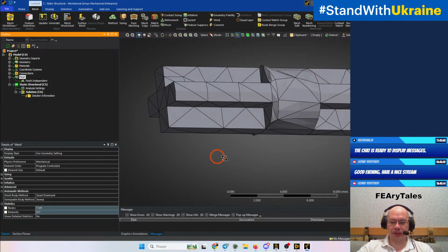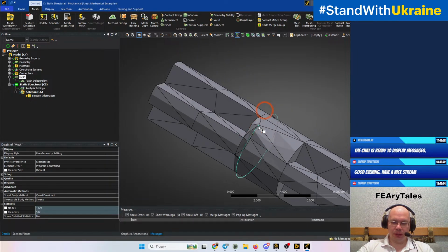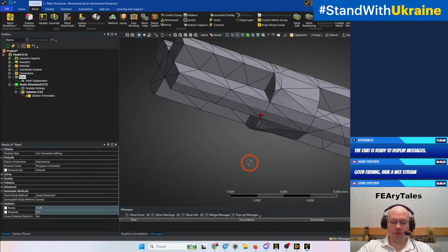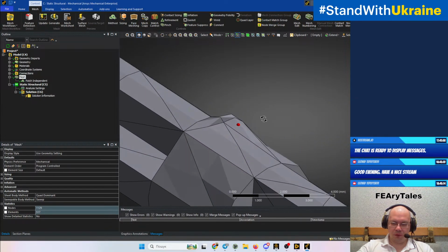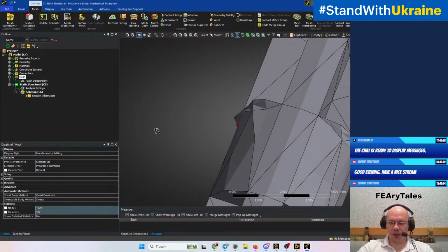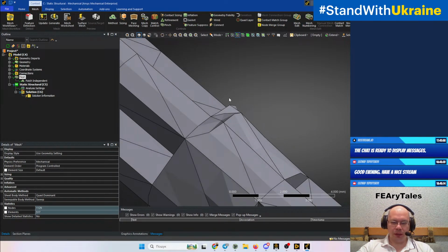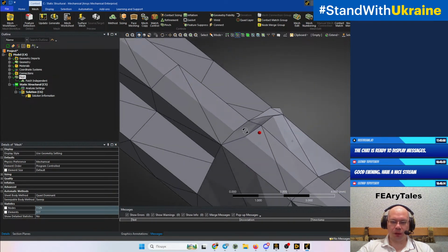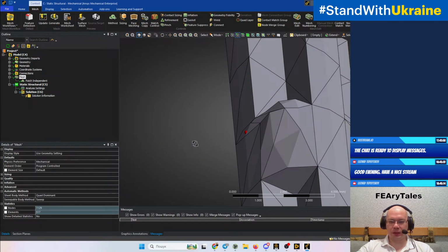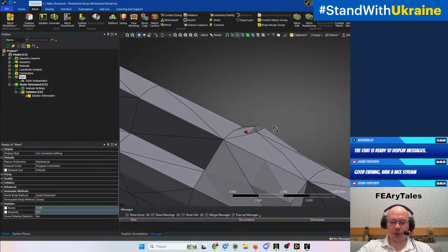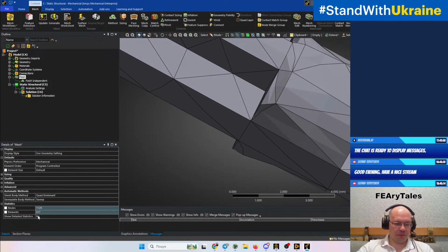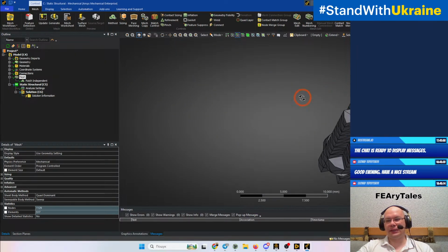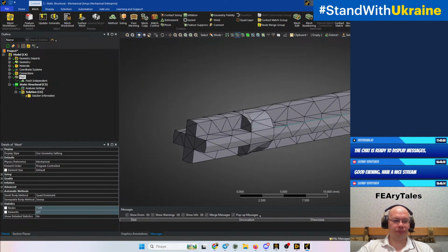Something like that. And as you can see, it defeatures very forcefully, and it creates very bad element quality. We will not check element quality for now, but even without checking, we can say that it's not good here. But as you can see, we have 500 of elements and 1000 of elements, so it's less than on a first attempt with automatic mesh.